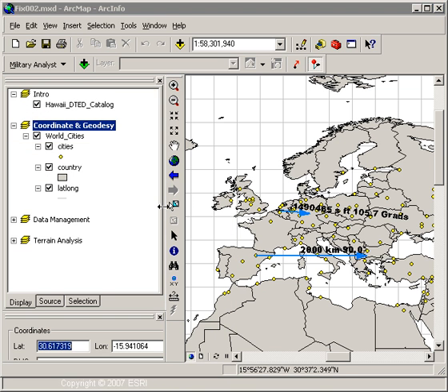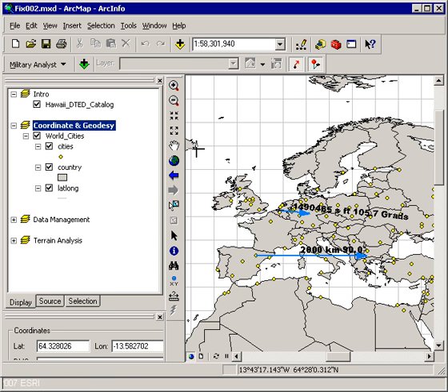The Geodesy graphic tool is very similar to Geodesy Calculator in that it is going to draw a geodetically correct line. But as I mentioned, it's an interactive tool, so I can basically just drag and drop my line across the screen between my two locations. I notice here that as I've drawn this line, it's calculated a distance and direction of 1,887 kilometers at 71.8 degrees.